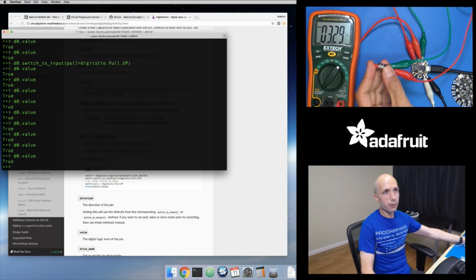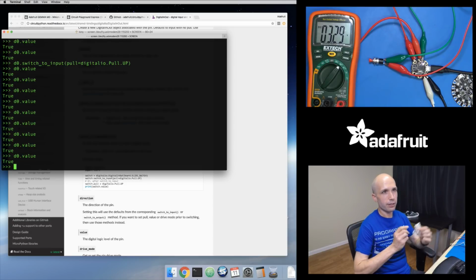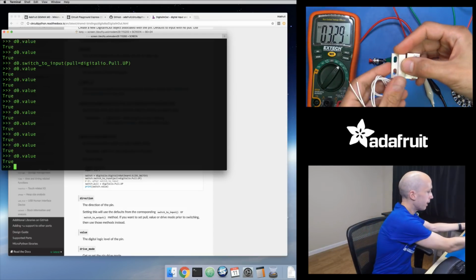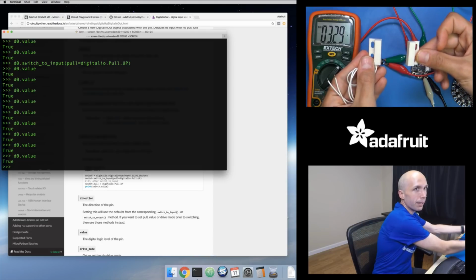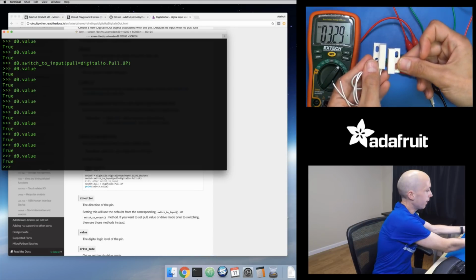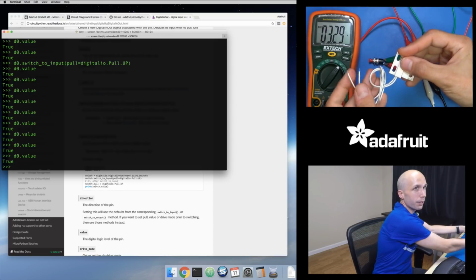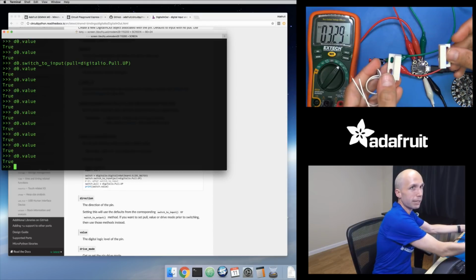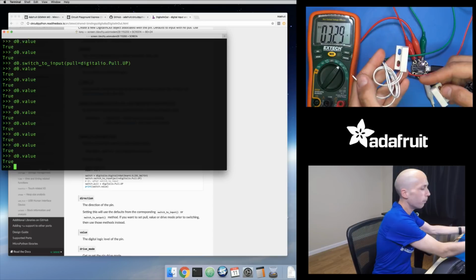So there are other things that give you a digital output. For example, this is a door detection sensor, a little magnetic sensor where basically there's a magnetic switch inside of here on one half, and then there's a magnet on this half. And so when the magnet gets near this switch, it actually changes the output of the pins here. It makes a physical connection. And then when this magnet gets pulled away, then it disconnects these two wires right here.